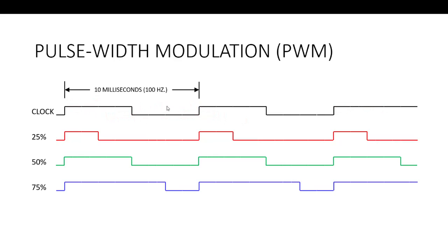That's our baseline. Now what PWM does is it allows us to put a digital input into that PWM input to a GPIO pin and determine what fraction of the time you really want the on time to be versus the off time. And that's called the duty factor. And here it's a 25% duty factor because it's on 1/4 of the time of the cycle. Here it's a 50% duty factor because it's on half of the cycle, as we can see, matches the clock. 75% is it's on 75% of the time.